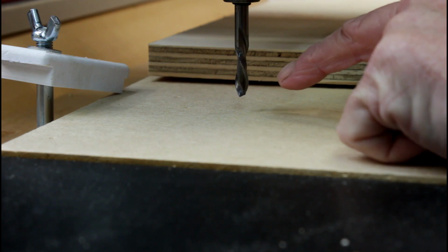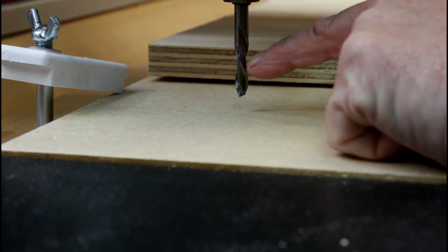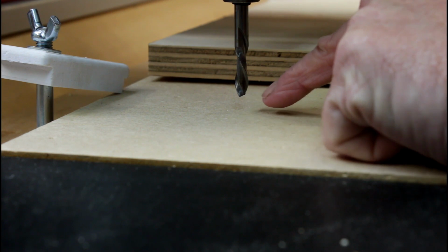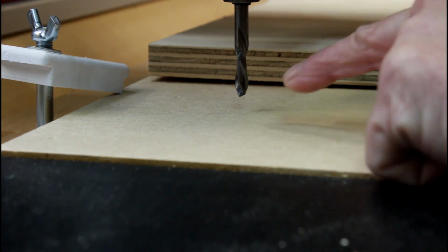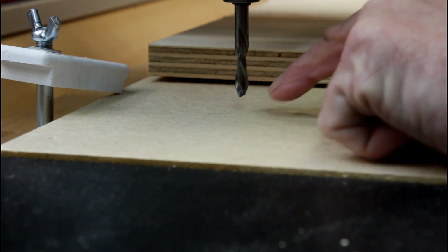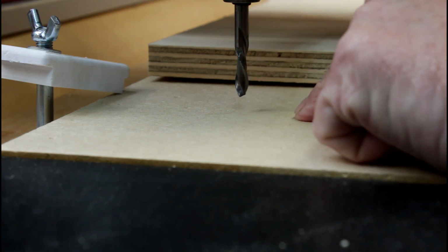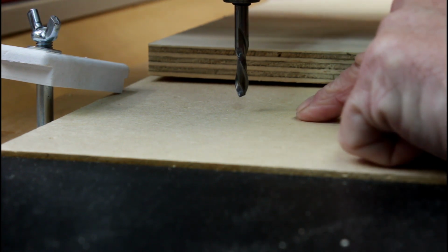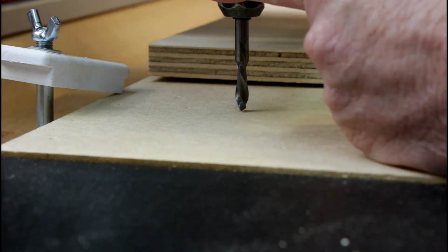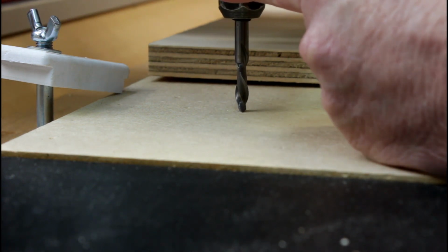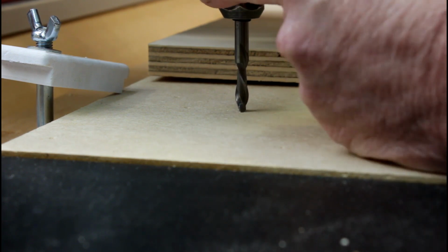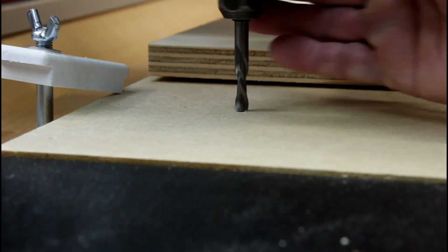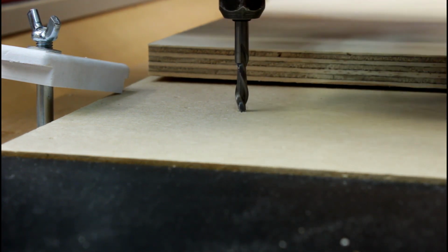Now those of you who have watched my videos should know by now that when it comes to setting my cutter, I like to set it to the tabletop rather than the surface of the stock, so that when I cut through my material I don't scar up my spoilboard. So I'm going to go and set that right now, and I'm going to use the usual method by setting it by eye. And there we are. Cutter is just touching the spoilboard and no more.